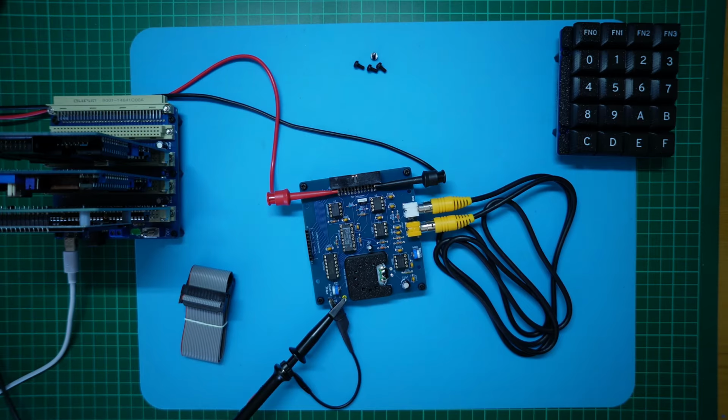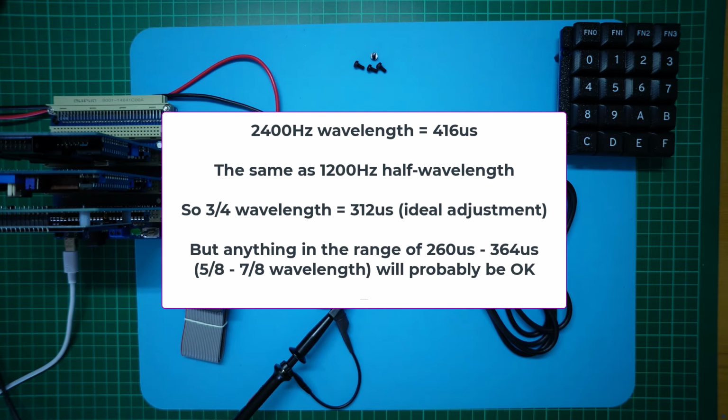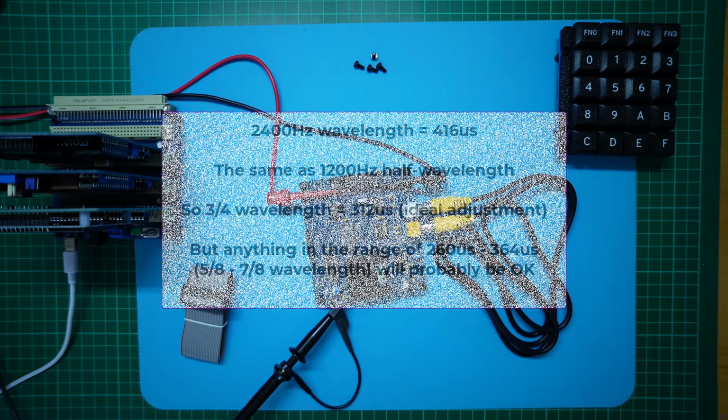Just to explain, what we're looking for is a delay which is approximately 3/4 of the wavelength of a 2400 Hz signal. At this point in time, the 2400 Hz signal should be low, whereas the 1200 Hz signal, being half the frequency, will still be high. And that state is then clocked into our flip-flop. So you do have a bit of leeway in terms of the 312 microsecond optimal setting.